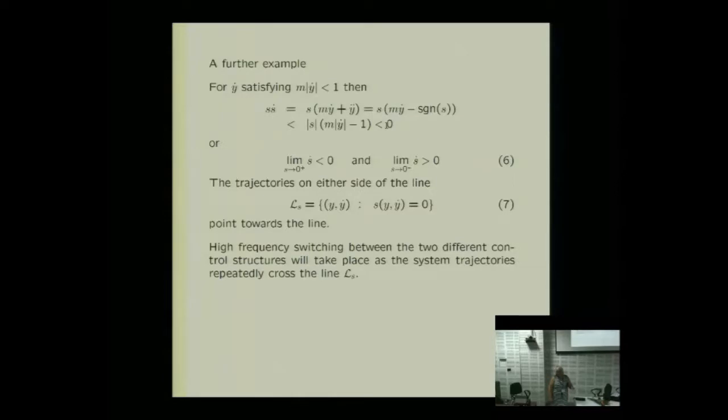But I'll already say why in this sliding mode paradigm, this control paradigm, which people spent a long, long time working on, has found it much more straightforward to get traction in the observer domain. And why we will be focusing tomorrow, and in some of our serious applications, on observer problems. Because for observers, of course, the switching makes no difference neither here nor there. An observer is sitting on a computer or some sort of embedded device. It's a bit of code. It can switch as much as it likes.